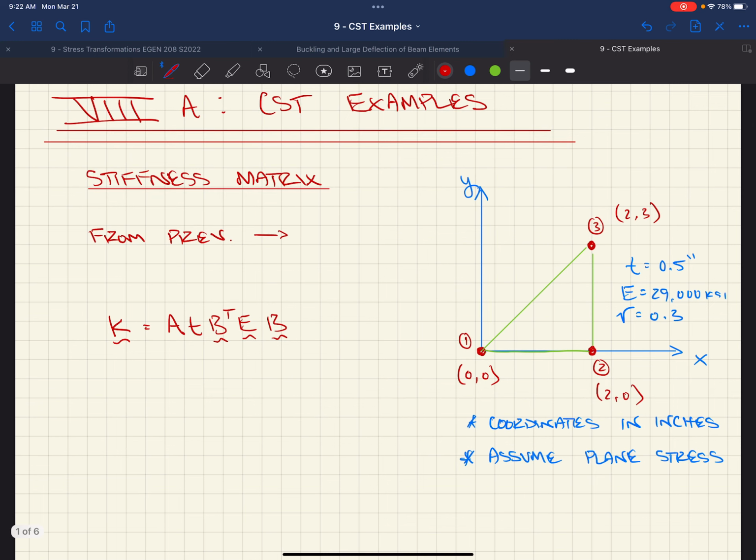That's why, because y1 and y2 are the exact same value. So that's why the stiffness... Because when I went through my validation here, the stiffness matrix has to be symmetrical, right? So if it comes out non-symmetrical, then there's something wrong.